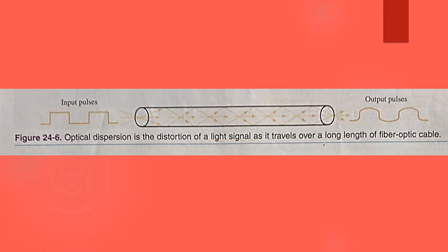As light is transmitted down the core, it is reflected from side to side. On a short run of fiber optic cable, there is no real problem with dispersion, but on a long run, not all the light arrives at the end of the cable at the same time. The slight variation in the time the reflected light arrives can be critical at high frequency rates of transmission.